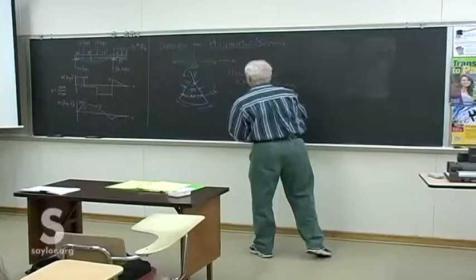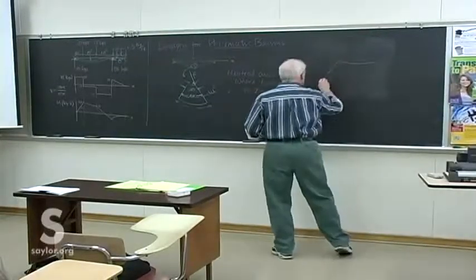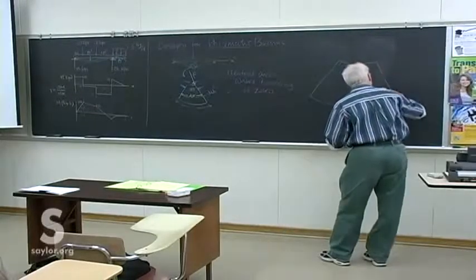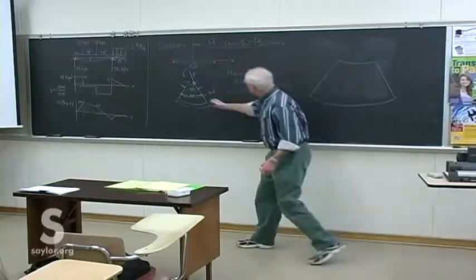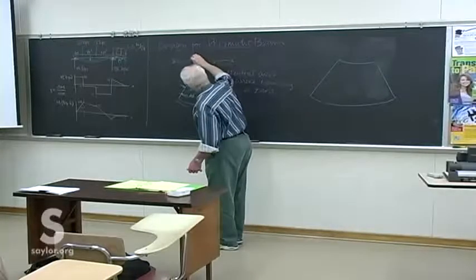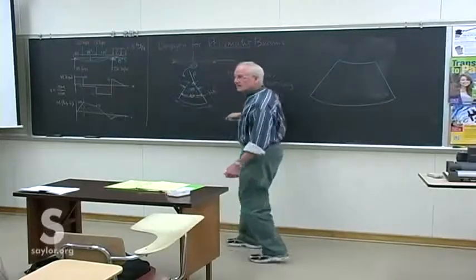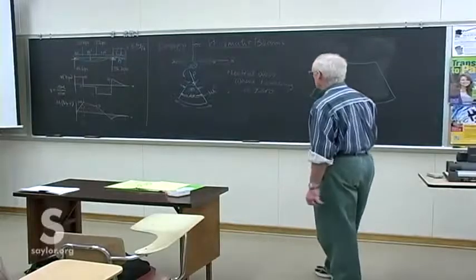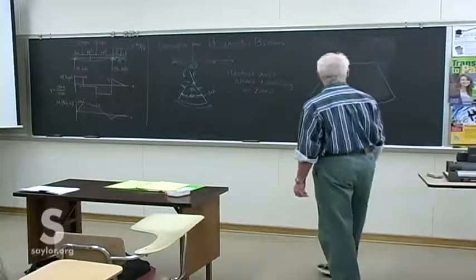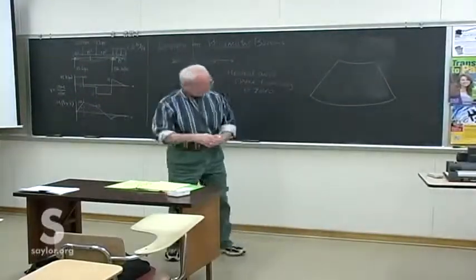So again, I'll take that picture and blow it up some so we can really see what's going on. Oh, by the way, these spots that were originally planes remain planar. There's no deformation of those, at least not with what we've got going here, because we don't have any axial loading. So these are still planar surfaces on the edges there.